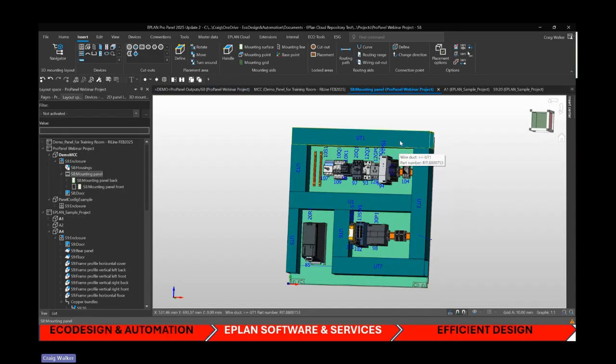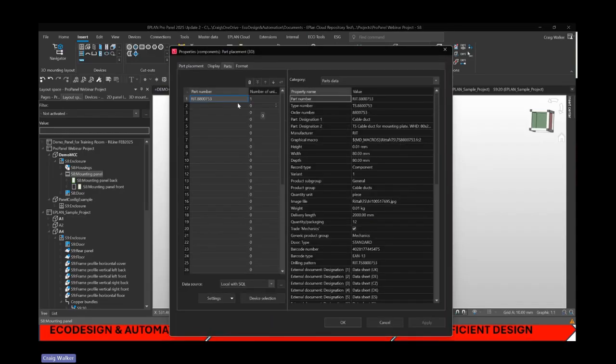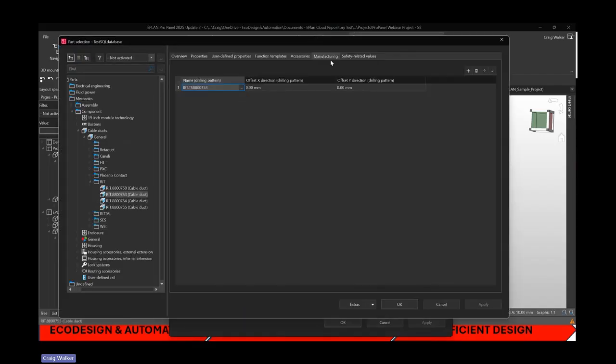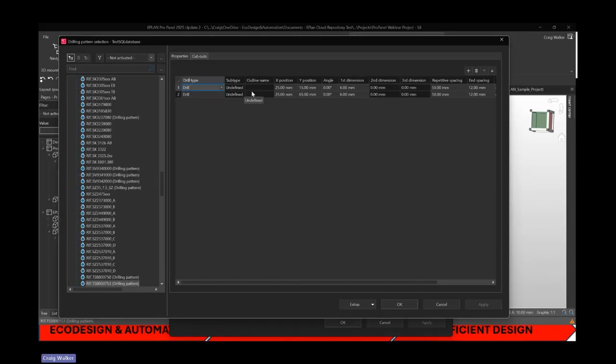And as I said, they've got drilling patterns. So if I was to open this up, this is obviously a right tail part, right tail trunking. And this has a drilling pattern from the manufacturer that's guaranteed to work and good to go. This is designed to have two rows of holes drilled. And you get options in terms of its repetitive spacing is 50 millimeters, but it's drilling every fourth hole.